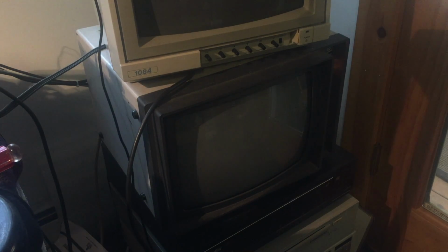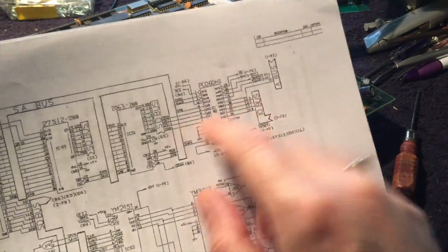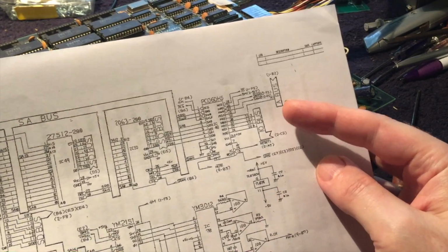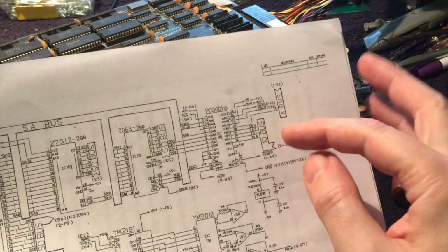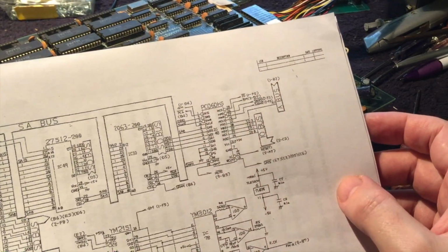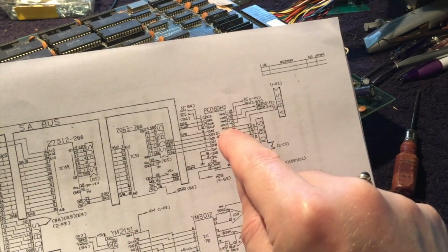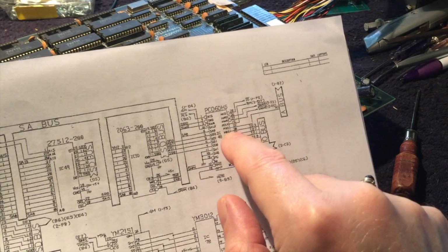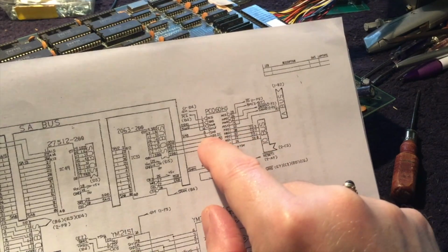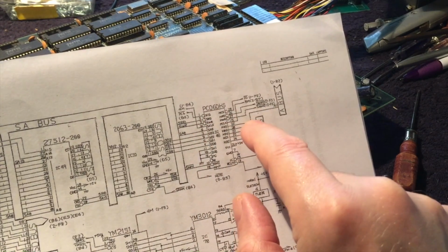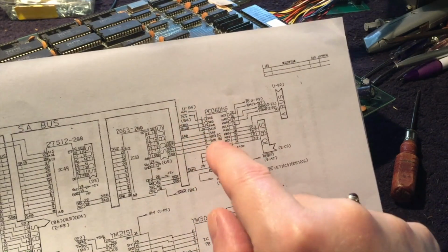Let's see if we can figure out if the main CPU is actually trying to communicate with the sound CPU. Now on this custom chip, there's basically 4 bits that pass through, and there's one address line, so I'm not sure if that means it can pass multiple chunks of data at the same time. This chip's not documented to my knowledge, so I don't know exactly how it works. But it looks like you've got clocks going in on each side for the master and the slave, because they're running at different speeds. It looks like the 68000 runs at 8 megahertz and the Z80 runs at 4 megahertz.